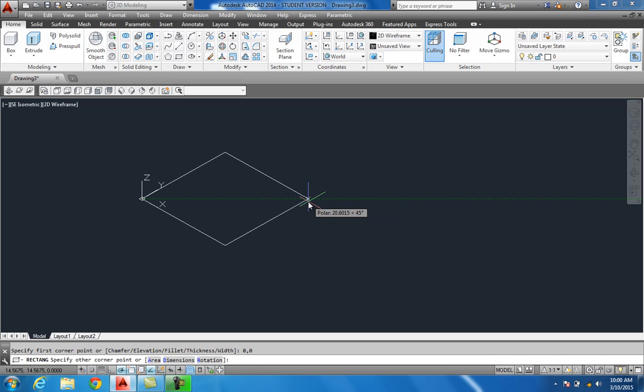Okay? And this is what AutoCAD calls its world coordinates. And you'll actually see it up here in the coordinates. You see World. This is its world coordinate system. If you ever change the coordinate system on this, or how you have it set up, go back to World and it'll switch exactly back to the original of what it is right now. So you'll never lose that. It'll always be there. And if you get off track and change things, you can always go back to the world coordinate system.